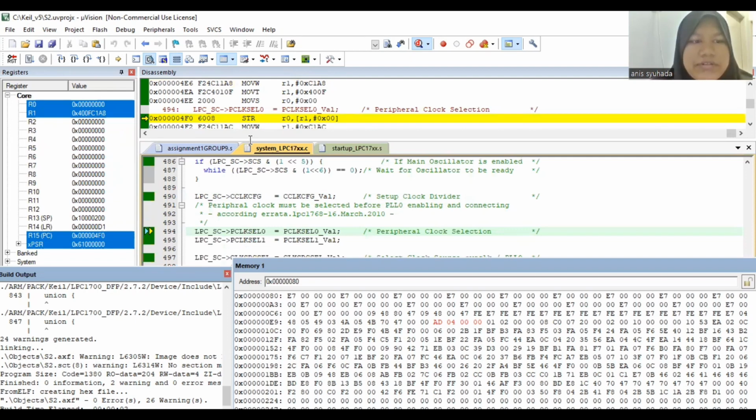The correctness of the data verifies that each word of data from program memory is accurately transferred to the corresponding frame address, confirming the transferred data matches the expected content, which might be a sequence of data stored in program memory, which is this register and this memory, 0x00000080.